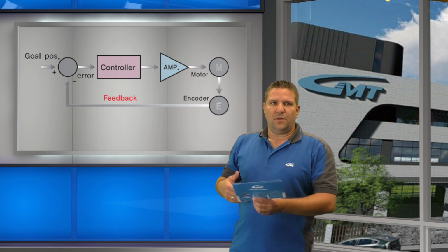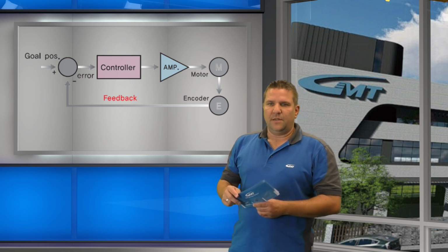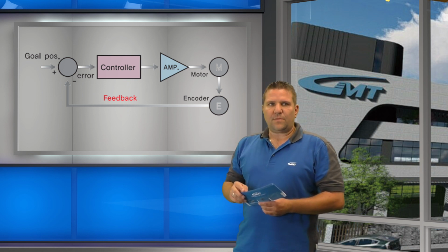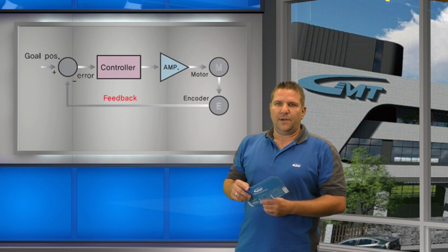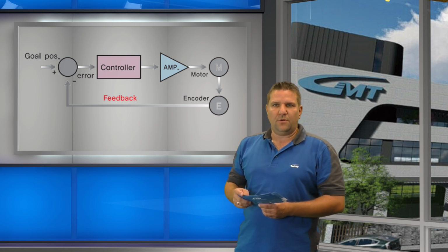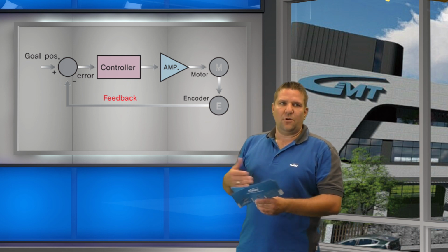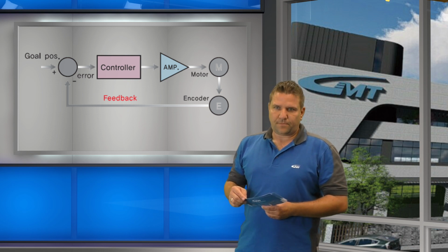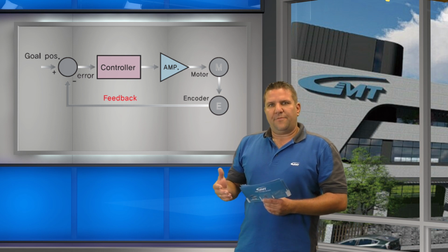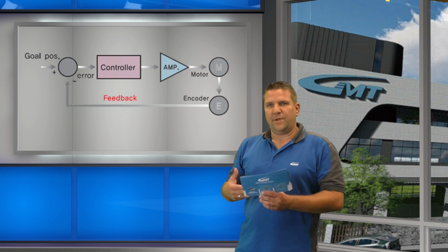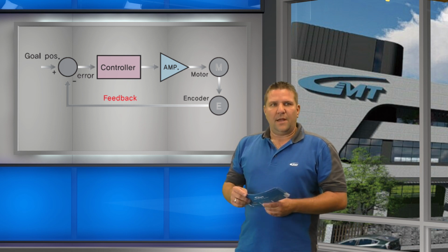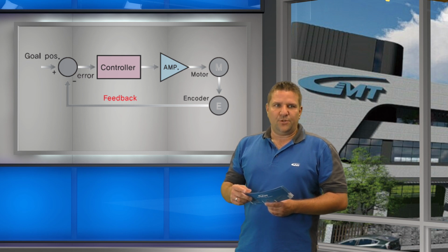But sometimes, because of the load or the acceleration, you will lose steps, and at that moment the encoder realizes that you have lost steps and directly gives feedback to the controller so that it can correct the lost steps. We have prepared something to show you how to run a motor, and this is explained by Torben, who will show you now.